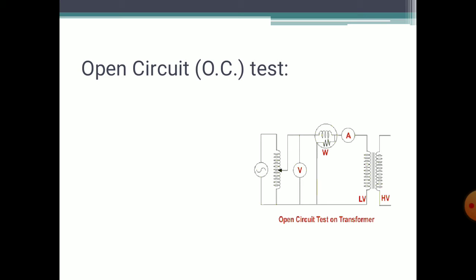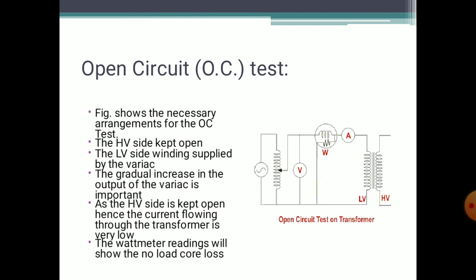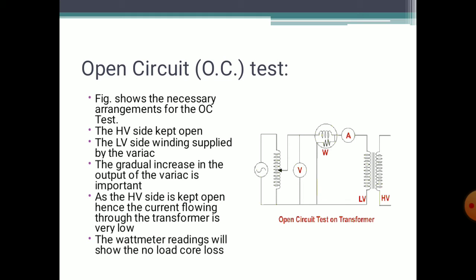In this open circuit test, the high voltage side of the transformer is kept open, and a minimal supply is provided by the variac to the LV side.